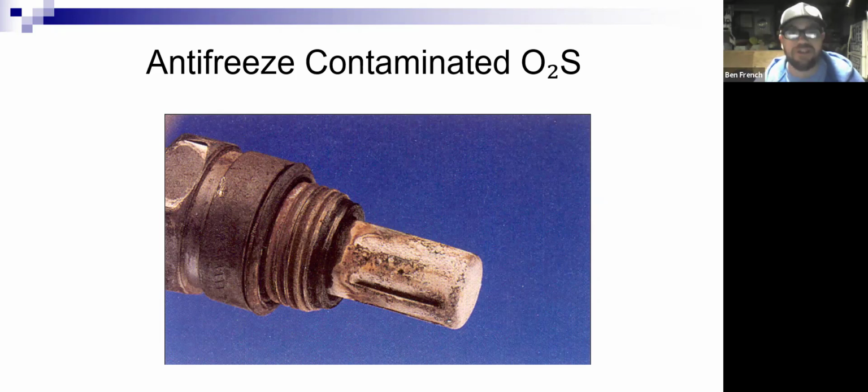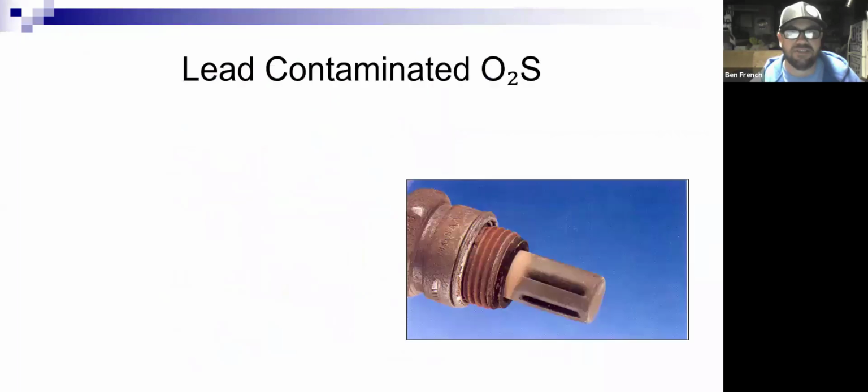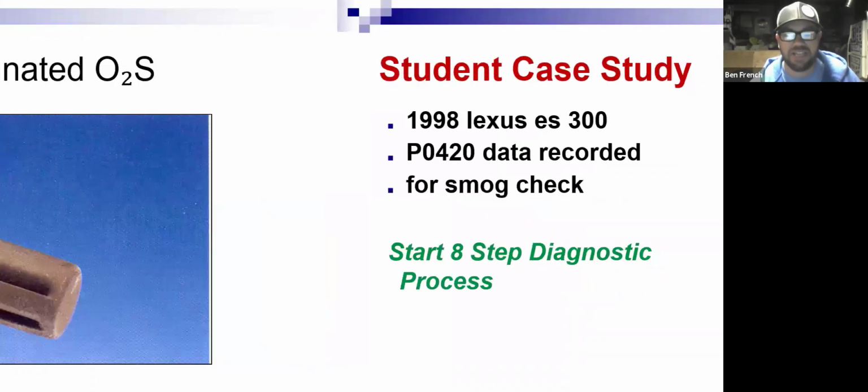And guess what? You know who else doesn't like that coolant pumping through there? The catalytic converter. If you keep driving on that blown head gasket, filling up the coolant, driving a little bit more and filling up the coolant again, you'll end up costing yourself more money in the long run. Because when you get the car fixed, before it's passing smog, you're probably going to need multiple oxygen sensors and even a catalytic converter, because the coolant will contaminate all those things. Leaded fuel, I mentioned that.